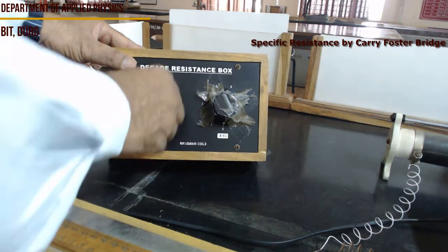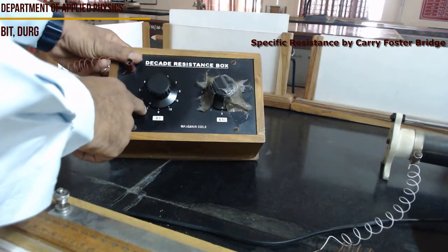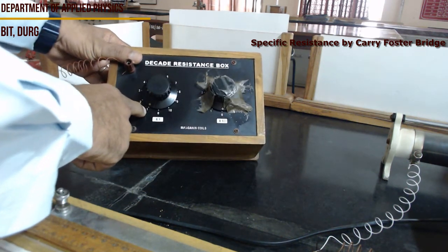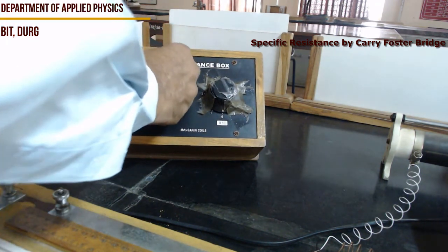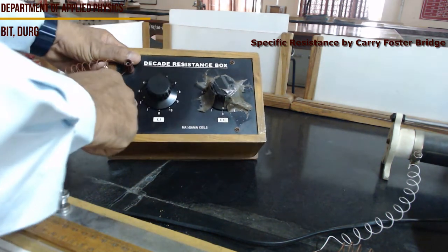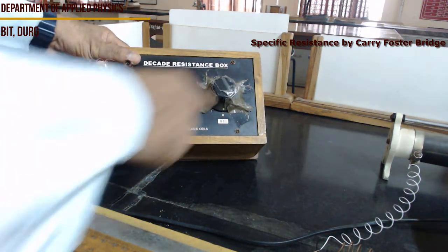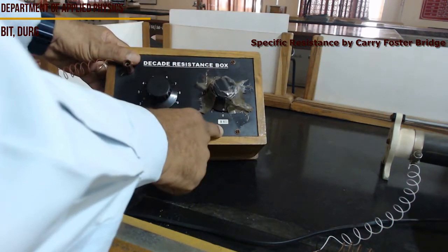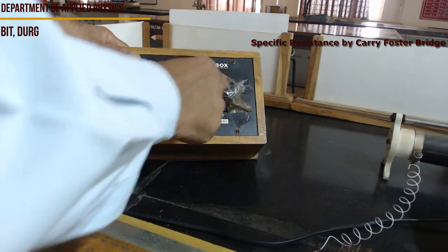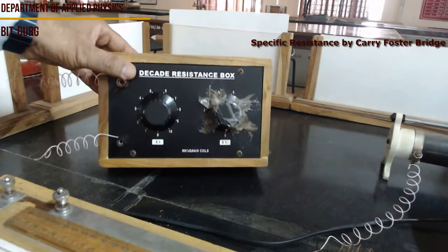Means whatever point you choose here, suppose we choose 1, then actual resistance is 1 multiplied by 0.1, that is 0.1. When we select 2, it means 2 multiplied by 0.1, which means 0.2. We are not using it, otherwise if we put this at 2, this means 2 multiplied by 1, that is equal to 2 ohms.